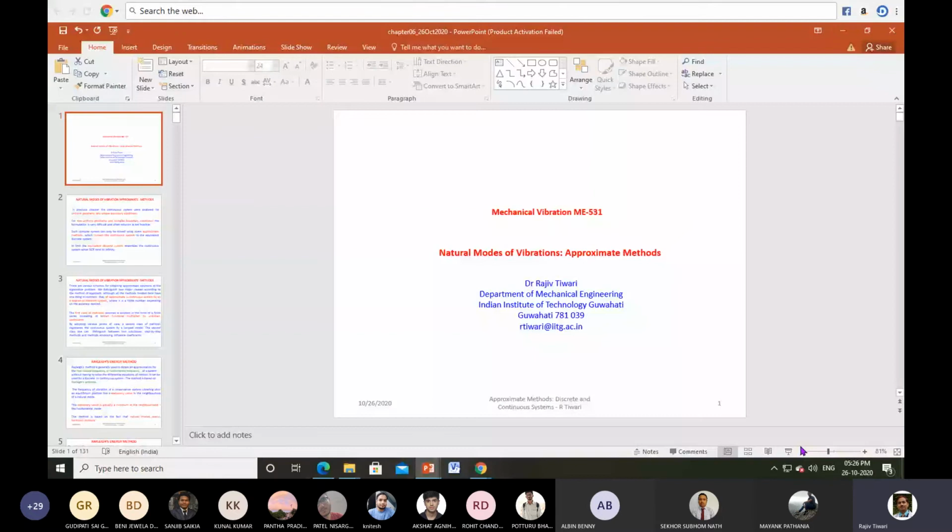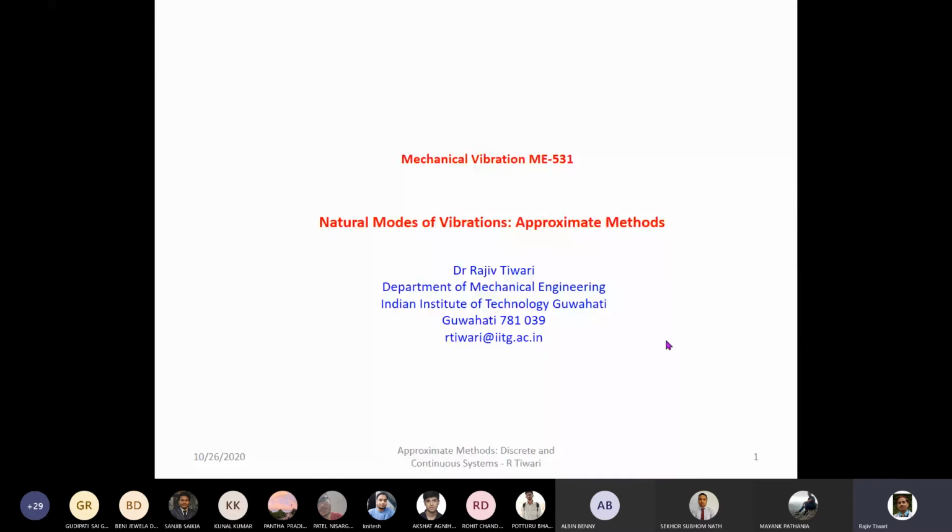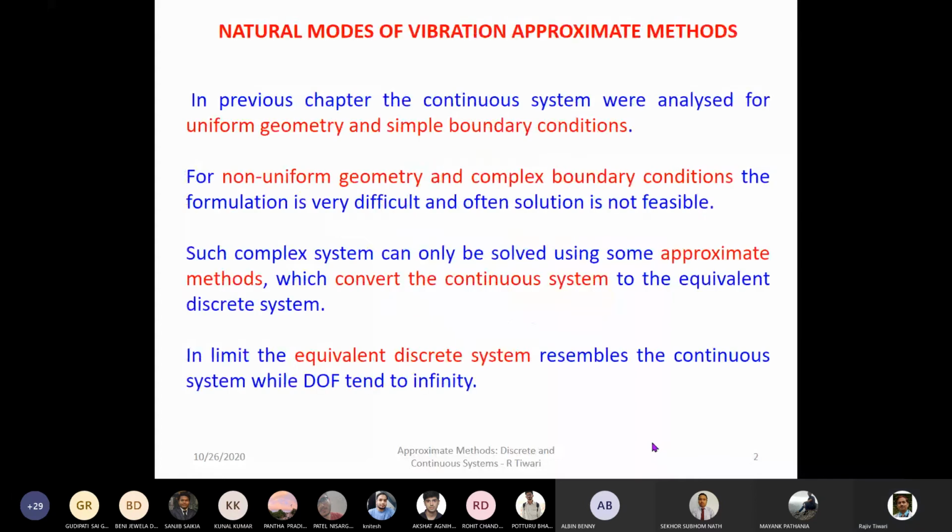Here we'll be focusing on finding the natural modes, natural frequency, and either eigenvector or eigenvalue. These methods are applicable to both discrete systems as well as continuous systems, and especially in continuous systems they will be very useful.